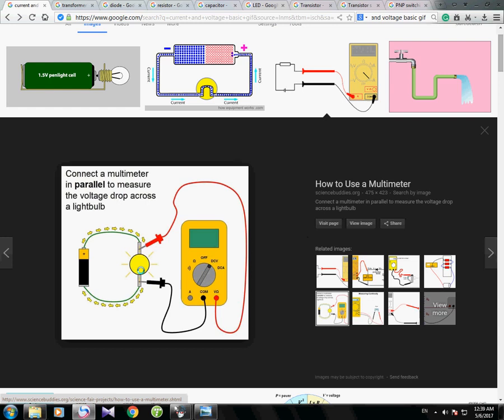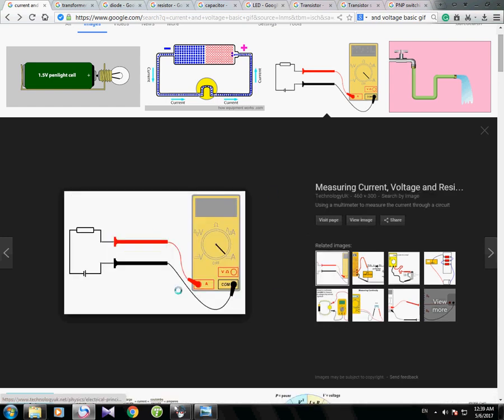Here you can see that DCV, that means DC voltage, is being measured. So our previous one was the series circuit, this one is an ammeter, so this one is a series circuit. Current will go through this meter and out from this meter and go to the load and come back to the power source or battery. If the meter is broken or disconnected inside, then the load will not work, so that is a series circuit.